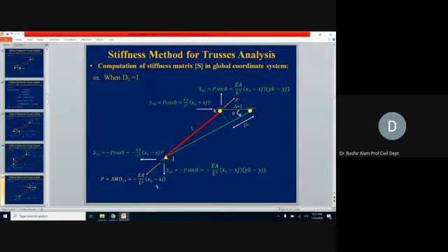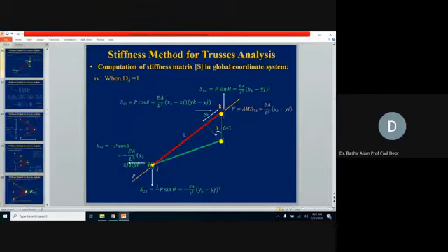Horizontal displacement was given. Similarly now, when we give D4 equal to 1, again if you see, from this green we are sliding it in the upward direction. So as a matter of fact, this should be red and this should be the new location we show with the help of the green line. Again, extension we see. Extension means because of the tensile force. This is how we fix the direction of this tensile force.